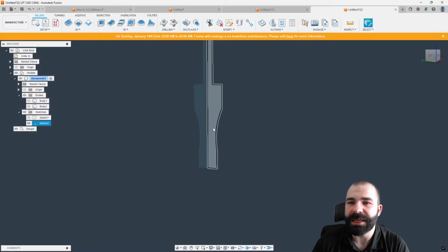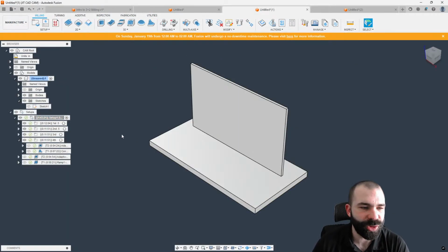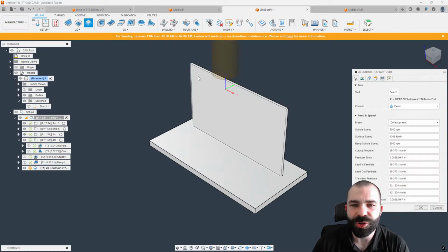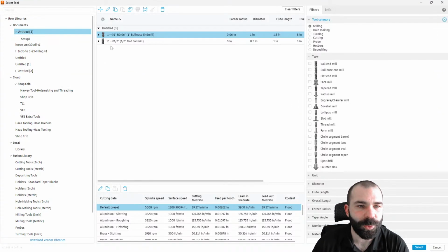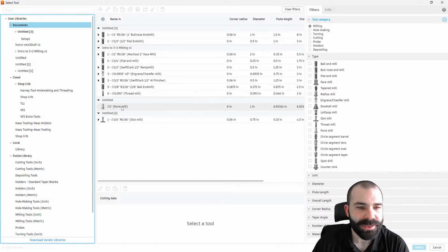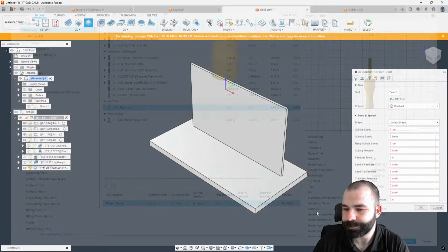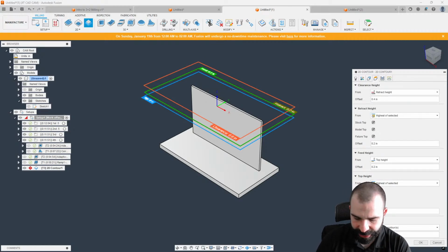So if I wanted to now use that tool, if I have a part I can put this on, sure, we'll do it on here. 2D contour around the top. Go grab that form tool. You need to jump across parts here real quick. There's my form tool. And let's just go ahead and say we're going to go a 1/2 inch down the part, right?